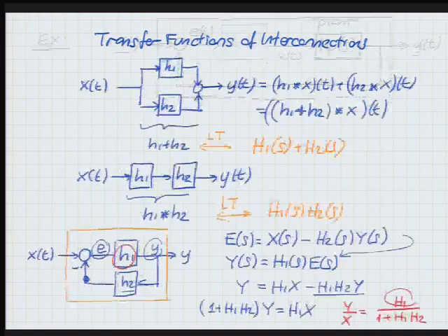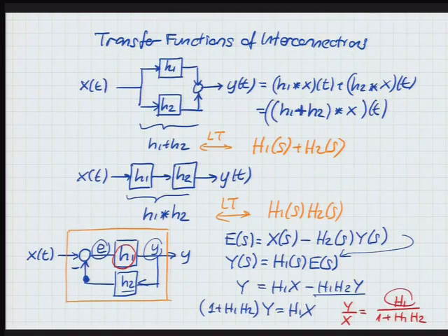Well, the general answer for this configuration is here. If in the feed forward I have H1, in the feedback I have H2, then the transfer function is H1 by 1 plus H1 H2, right?